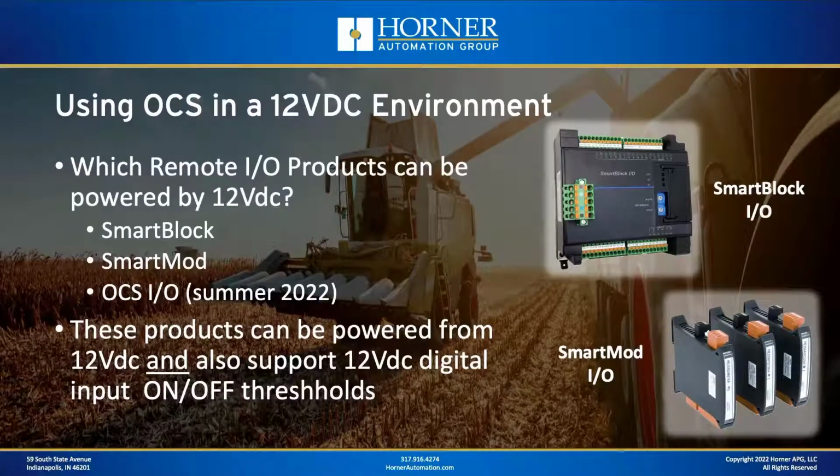If you're talking about expansion I/O, what if you need to add some additional I/O and you're looking for 12 volt compatible I/O? Well, there your choices are a little more limited than normal. You're basically looking at Smart Block, Smart Mod, as well as the new OCS I/O that we'll be releasing this summer. So these products, again, are compatible with 12-volt supply power, and they have the appropriate on-off thresholds to be supportive of 12-volt inputs.